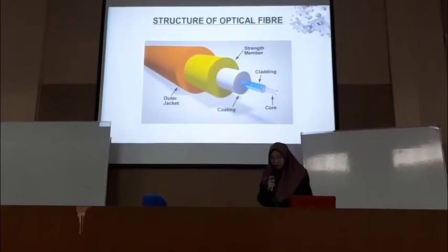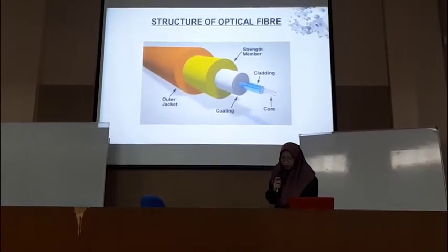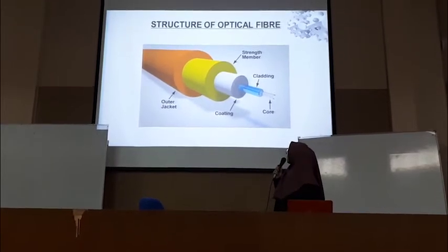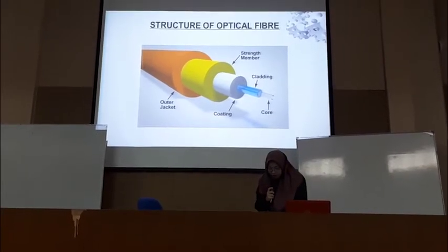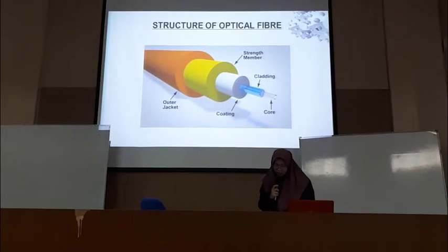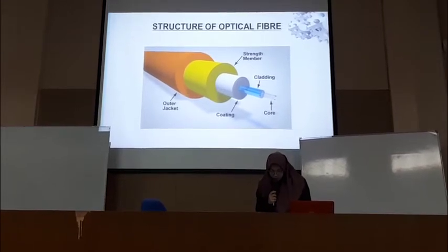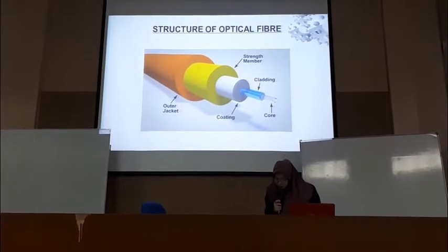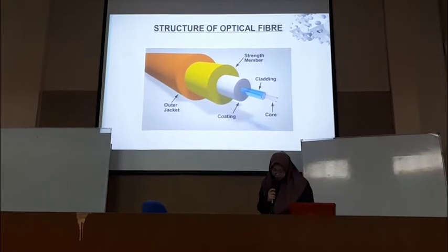In order to better understand how fiber cable works, one should have a look at its components. When stripping an optical fiber cable of its layers, the following components can be observed: outer jacket, coating, core, cladding, and strand member. Core and cladding are typically made of glass or plastic. The more important specification of the core is the index of refraction, which is the value of light bending passing through the material and the speed at which light can travel through the material.